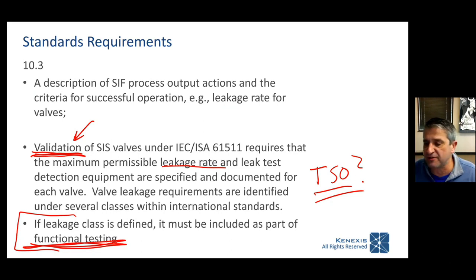And there are a variety of different ways to do that. Oftentimes, this requires you pulling the device out and taking it to the maintenance shop. Now, it gets even worse because if it leaks more than you specified, you've got to send it back to the manufacturer to get rebuilt, refurbished, relapped, new fittings, maybe seat replacements, depending on whether you have a soft seat or a hard seat.